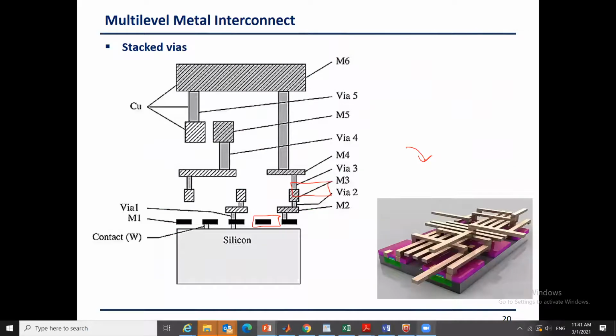This is somebody who took a chip and really just showed the metal wires, so it is like maps of roads that we see in real life. But the difference is that the gaps that you see here are really filled with insulator. There are no gaps, there is really insulator between them, which also helps the structural stability of the chip, and the insulator helps reduce the coupling.